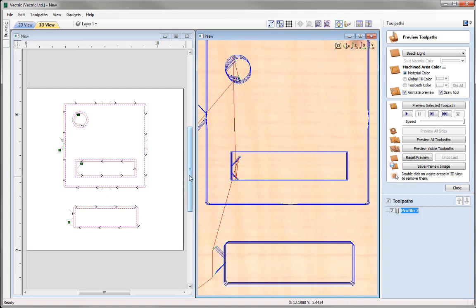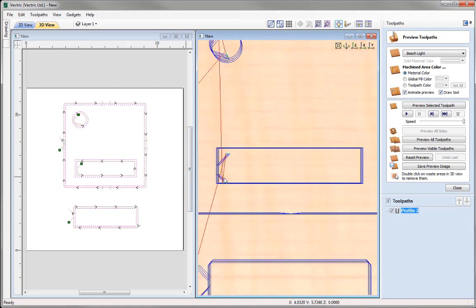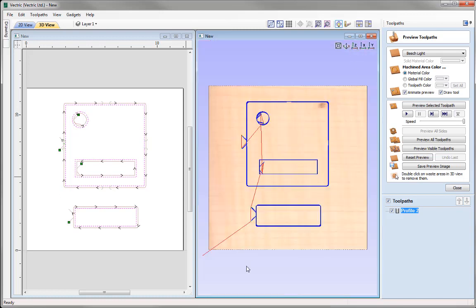If you take a look at the actual lead out, you can see it's much shorter than the lead in, but that's okay. That's not going to cause us a problem, as we still have a lead out. It's just been clipped. So if we put that in Z, we can again slow that down.